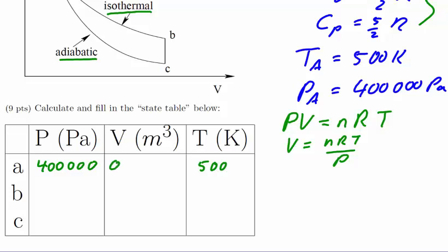The result is 0.0207875. As always in these problems, we're keeping lots of digits since we recognize that at the end of the day, accurate answers will require that we keep many digits throughout the problem. The text of the problem specified that the volume would quadruple in getting from point A to point B. Therefore, we quadruple the result that we have to find that the volume at point B is 0.08315.